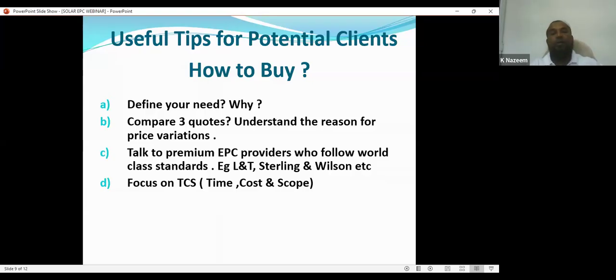Then after 1 year or 2 years, I saw the news in the media. The complete solar power plant was blown away due to wind. So what was the root cause? The aluminum structure given by the vendor was so thin and so flimsy, it was not durable and did not withstand the cyclonic winds. So the complete plant collapsed. Then so many other issues must have erupted, like legal issues, safety issues, and other things.